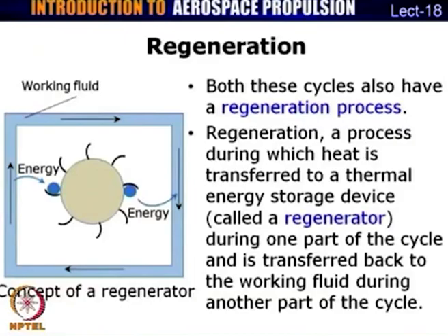Regeneration is a process which is common to both Stirling and Ericsson cycles. Regeneration is basically a process which involves heat transfer to a thermal energy storage device, which is a regenerator, during one part of the cycle, and the energy is transferred back to the cycle during another part of the cycle. It is just conceptually shown in this diagram here. Here we have a cycle which consists of a certain working fluid which has a certain energy associated with it, and there is a thermal energy storage device, which is a regenerator, placed at the center here.